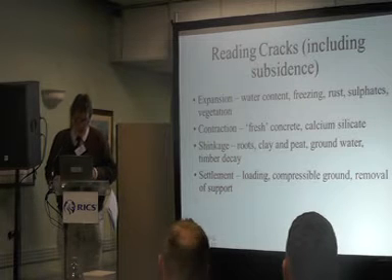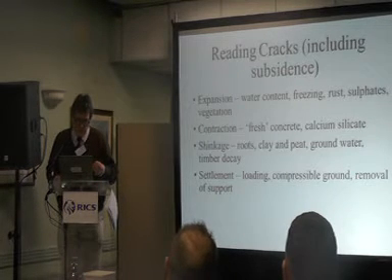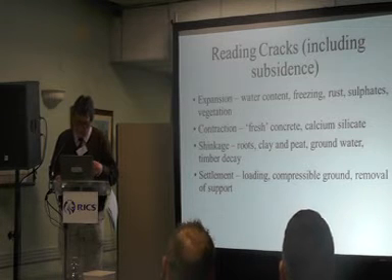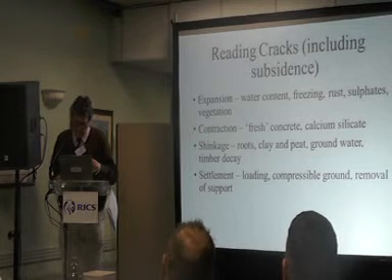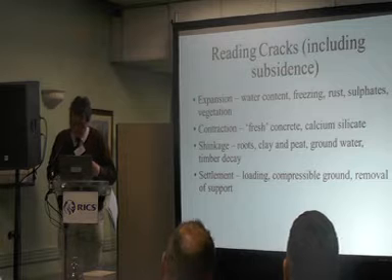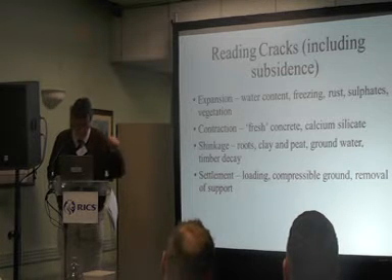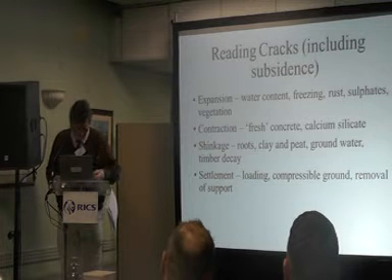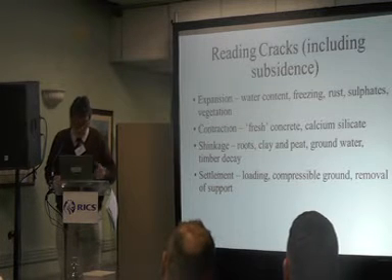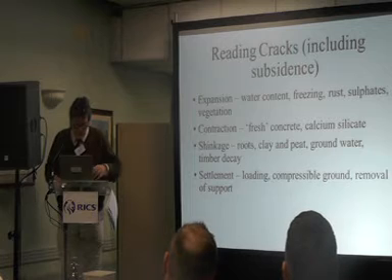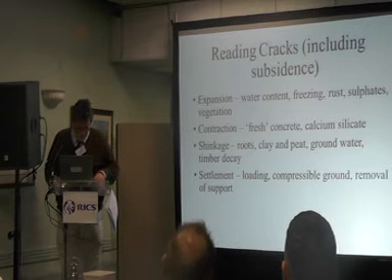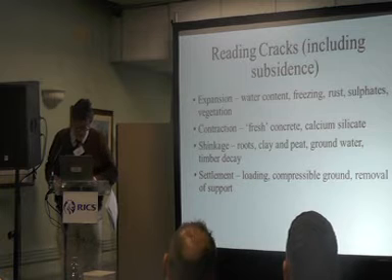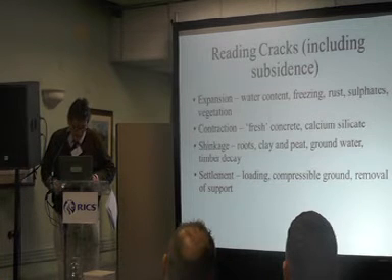Sulfates, I'm not going to go into much detail on sulfates, but where we come across sulfate damaged brickwork, it is a real difficult problem, and it needs a proper technical look. You'll know when you've got it because you'll be able to stick your penknife in and it's gone soft, it's lost its integrity, it's gone almost pasty inside. Vegetation, of course, roots and things, expanding walls.